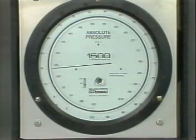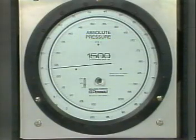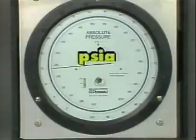Some pressure instruments, however, measure and indicate absolute pressure. Absolute pressure is measured without regard to atmospheric pressure. That means that the complete absence of any pressure, or a perfect vacuum, would result in a reading of 0 on an absolute pressure instrument. A common unit of absolute pressure is pounds per square inch absolute, or PSIA.